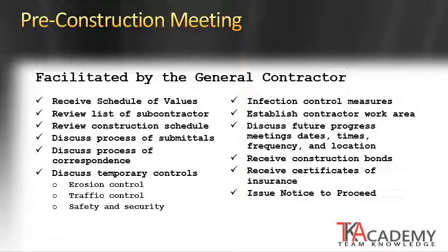The established contractor work area, also sometimes called the bed down, where they're going to set up their temporary job trailer, what type of utilities they are going to be able to use, where materials are going to be stored, and so on. Discuss future progress meeting dates, times, frequencies, and locations. So this is usually the first meeting of several that will occur during the progress of the project.